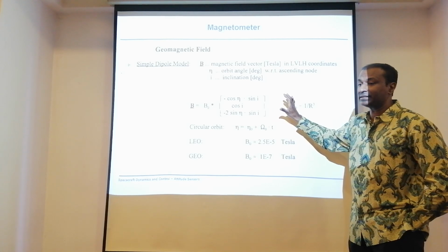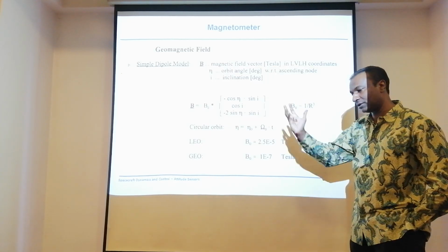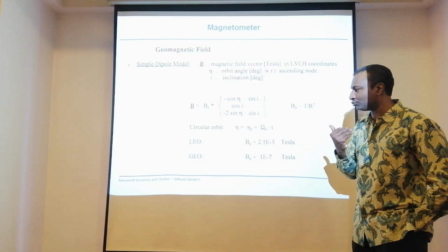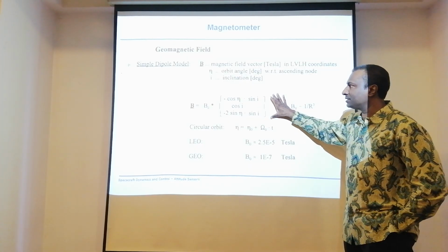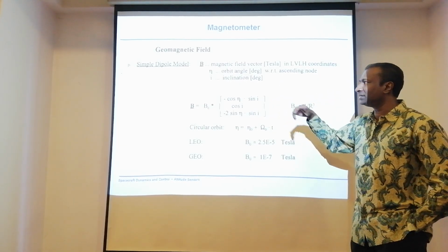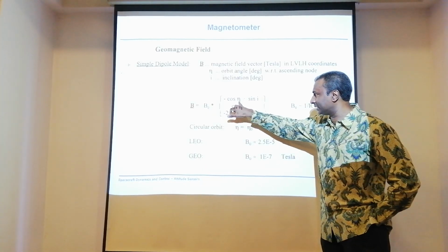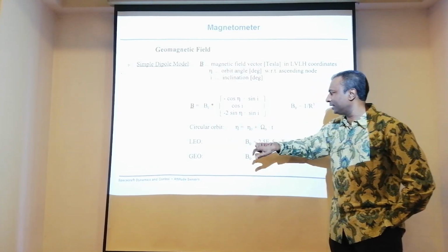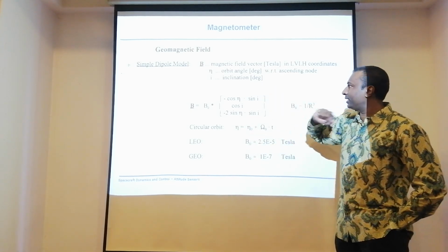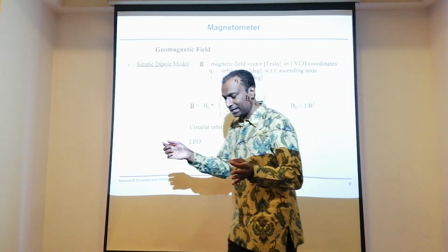In fact, I've shown this in the disturbances in an orbit. Then we went into the actuator, magnetorquers, and again this has been re-invoked for the attitude determination. So it's a simple model, a simple dipole model. Attention, theta basically is shown here. In this case, for a simple calculation, theta is basically the orbit angle with respect to the ascending node. So for a start, you can assume that it's exactly at zero.